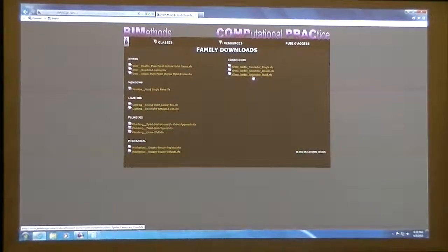But there are methods where we could just add some visibility graphics to the quad, and you can make it where you turn off the top left or top right, the bottom left and the bottom right, and you'd still get the same configurations as a double and a single. So this would be an example where someone didn't really understand all the ways that you could add additional parameters into one thing, and they ended up modeling probably the quad and then creating different files to achieve the same situation or configuration.